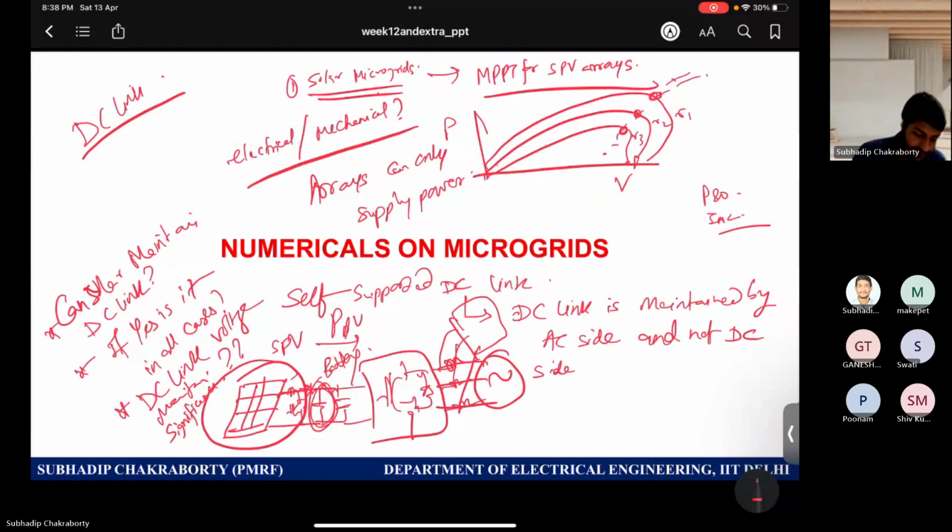So for the DC link voltage, you can push the power and some part of it can be utilized in the capacitor to keep it charged. Once you charge the capacitor and your power balance is met, that is, the power coming in is going out, the capacitor will remain charged to the value it was previously charged to. You can use the control to maintain its charge, and no additional power will be taken. Only some small losses will be there. Otherwise, no additional active power will be consumed to maintain the DC link voltage in further stages of operation. Once it is maintained, it remains maintained. Only some small losses you have to supply.